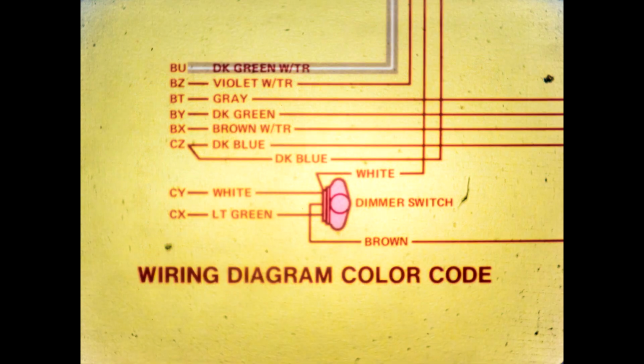The wiring diagram is one of your most valuable tools for troubleshooting a car's electrical system. Your technical service manuals contain wiring diagrams or schematics like this for all AMC cars and Jeep vehicles. These diagrams use drawings of the various working devices rather than more technical electrical symbols to help you locate a particular circuit quickly by visual association. The wiring diagram lets you trace a circuit on paper. You can see where a particular wire goes and how it should be connected without having to remove an instrument panel or cut open a wiring harness.